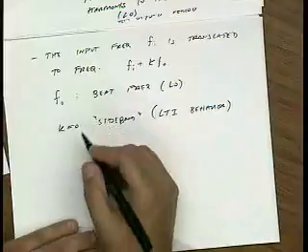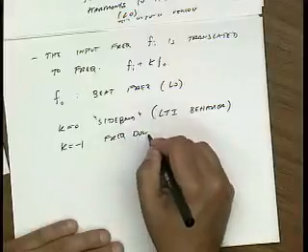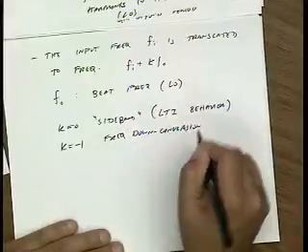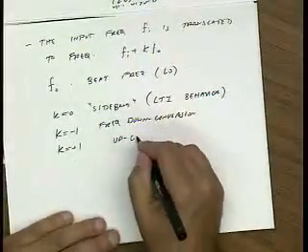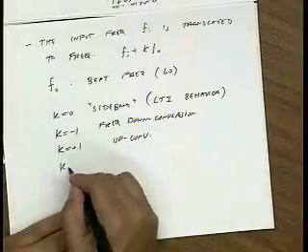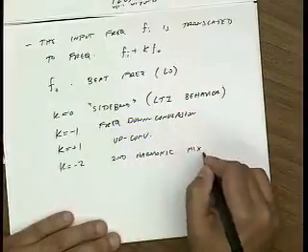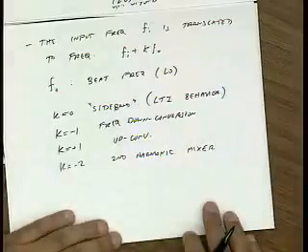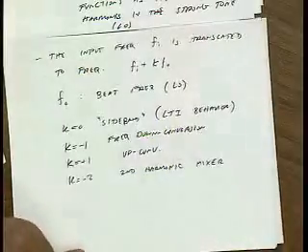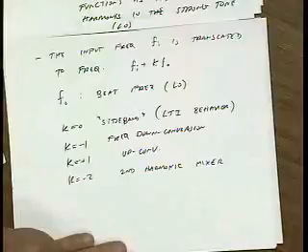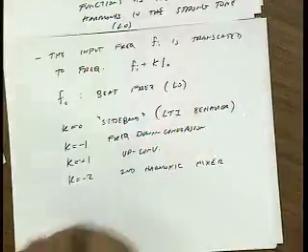Okay. K is equal to -1. That's frequency down conversion. Okay. K is equal to +1 is a normal up conversion. And so on. So K equal to -2 is second harmonic mixing. And so when we do our PAC analysis, we have to tell it which sideband we care about. Okay? And then that's it. It's just like doing regular AC analysis. You supply your input frequency and the sideband, and then you plot the output frequency.